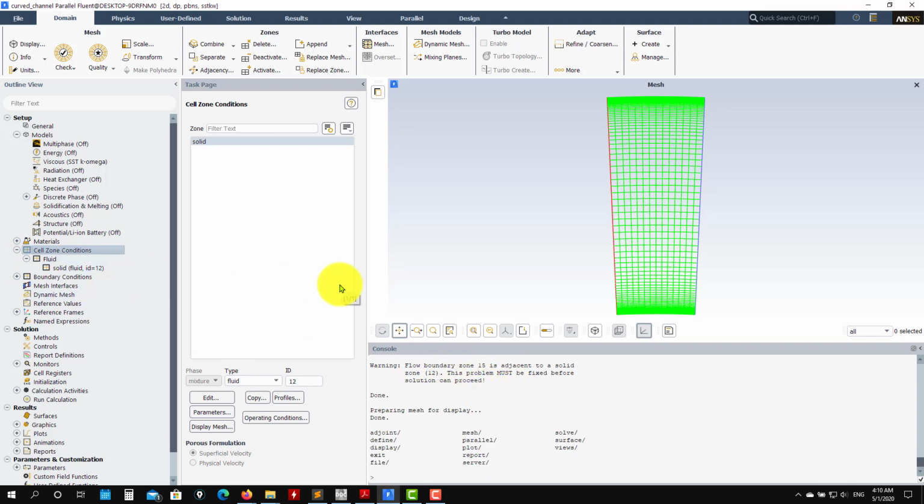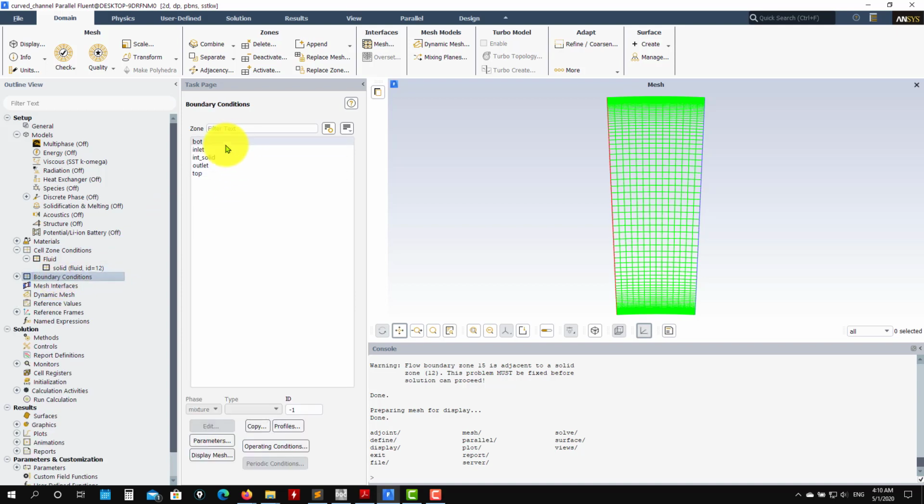The next thing that I want to do before changing to the predefined case is that here we're going to use periodic boundary conditions, okay? So far we have these two patches. So you go here, see that our mesh is defined. You have inlet, outlet, and the walls, okay? But we want to use periodic boundary conditions.